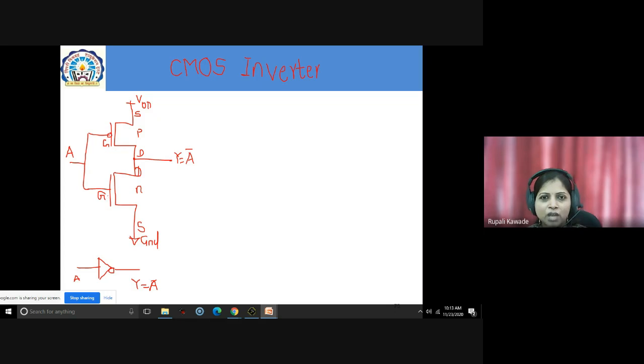Once you have a CMOS combinational design, the next step is to initially draw its stick diagram. The simplest way of describing a stick diagram is that it is a rough sketch of your layout. All the layers and diffusions are shown with the help of a single line. There will be no thickness, length or breadth. Simply, each diffusion is shown with the respective lines only.